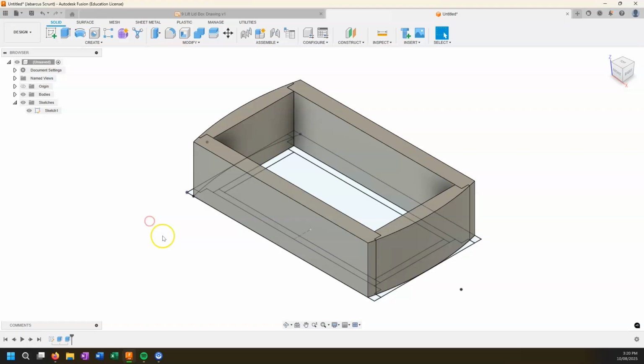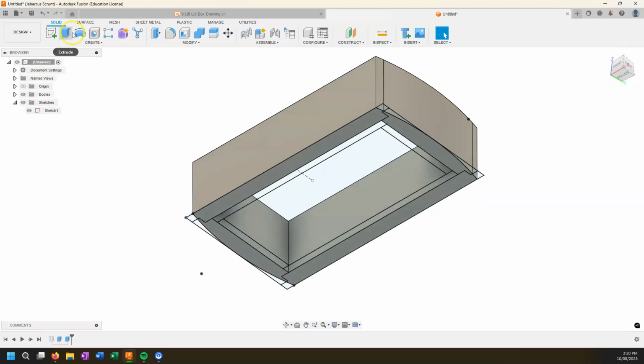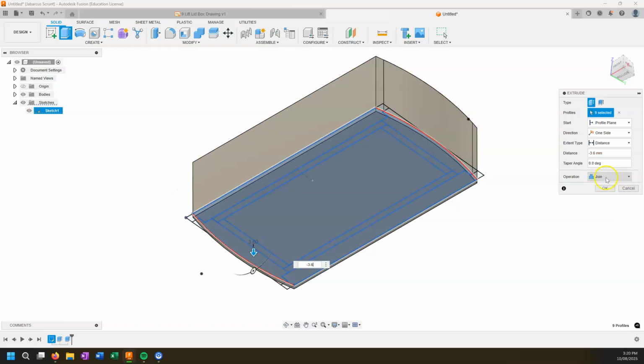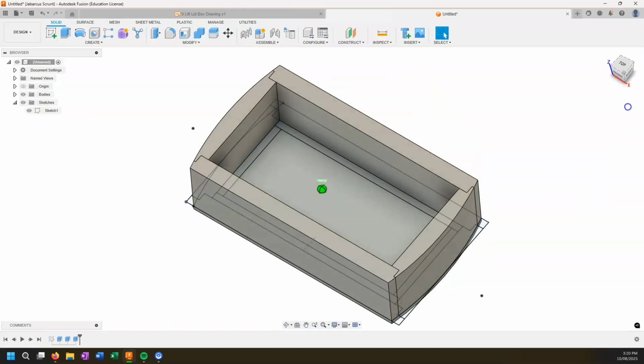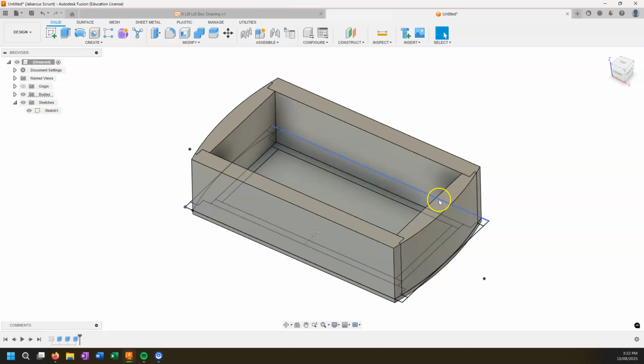All right, so now I can do my base. I can do my inserts. So I'm going to grab the cube, rotate around to the bottom, go to my extrude tool again, and this time I'm going to click on all of the sides, including all these inside ones. So the whole bottom will be kind of covered in, and I'm going to extrude that down. So it'll be a negative 3.6 for me. Just make sure it's going down. Again, make sure your operation is set to a new body. Hit OK. Rotate your cube back around, and now, let's just delete that.